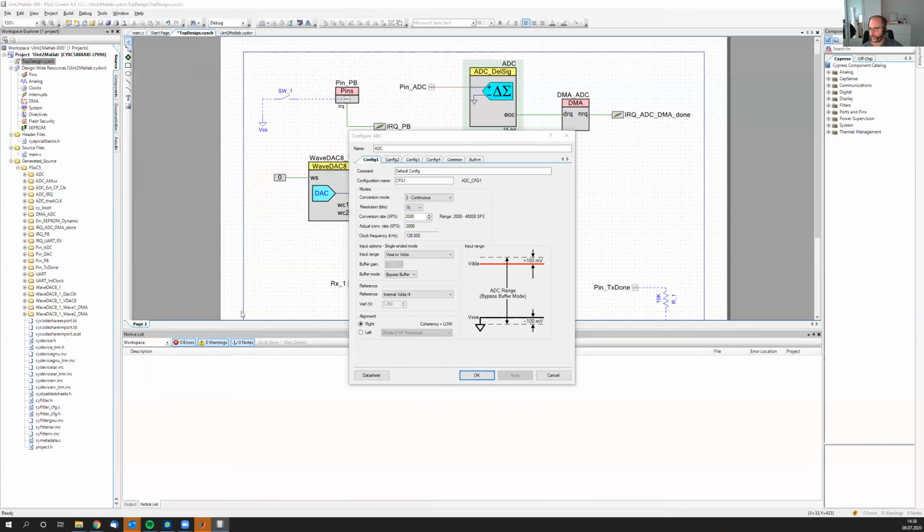So if you think about it, like for example, LEDs, they have a certain voltage and it's always the same voltage, okay? No matter what. If you have the LED together with a resistor, and no matter what voltage you give into that circuitry, the voltage over the diode will always be the same, okay? So this is fixed. And then you could, for example, use such a small circuitry, so kind of a voltage divider, but with an LED, and simply use this as a reference voltage, because this is fixed. Yeah. This is one way to do it.